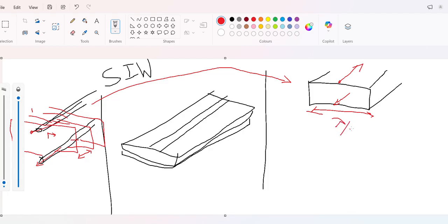Now, when we are talking about lambda and lambda by 2, all these are actually different. In case of waveguide, this lambda is not lambda 0, but your guided wavelength, which is a resultant wavelength because of how the wave actually propagates inside the waveguide. Because it bounces back and forth, there is a lambda guide, lambda g, which is higher than the normal lambda. So this is the lambda g of your waveguide.